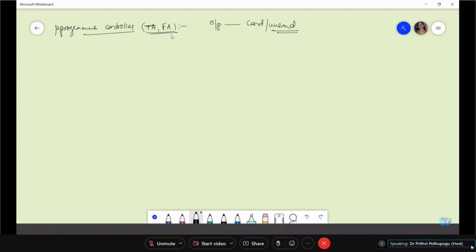That means it requires two instructions per output. For a single output, it needs two instructions, and it becomes a burden to the hardware. So that's why one aspect of Wilkes is to remove any conditional outputs and change them into a stable state, so that you can make it a perfect true address and false address. Between two state transitions, you will be putting that micro instruction. So the whole of the instruction should be accommodated within that micro instruction. That is the concept of Wilkes.